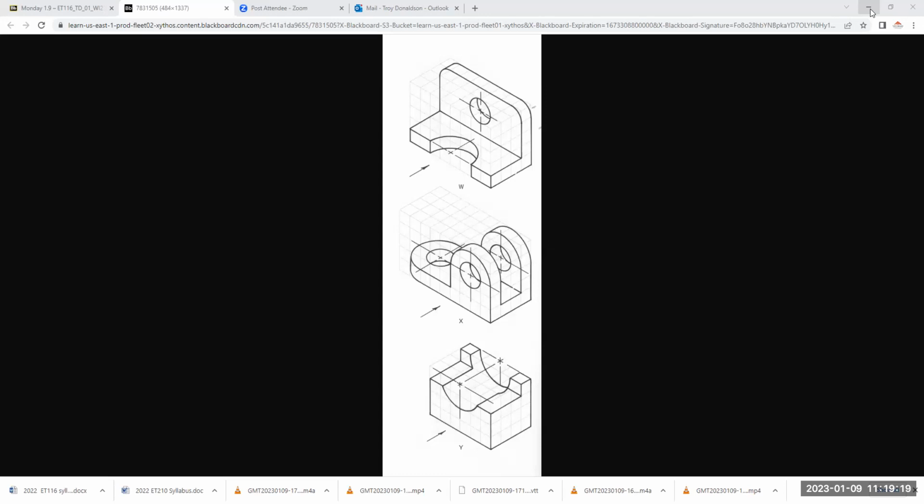I get to see the paper. So this is called paper space. This is model space where we draw the model. In paper space, there's a viewport, and this viewport is how we see the model. So it's like cutting a hole in the paper and allowing us to see this model, right?